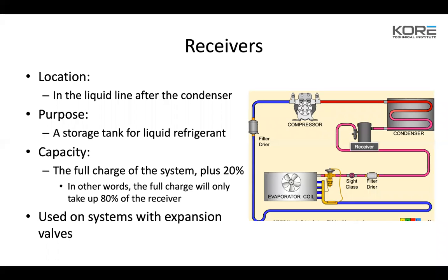So what happens here is those valves hold back refrigerant. If you have a 10-ton condenser, they're going to fill liquid into that condenser halfway through it to turn it into a 5-ton condenser. And that's going to help keep the head pressure up. The reason we want to keep that head pressure up is because we need over a 100-pound pressure drop across the expansion valve to push that refrigerant through it to boil off inside of the evaporator. So that's why we have to maintain that head pressure. The refrigerant is going to want to migrate to the condenser, so you're not going to see it in your receiver. It's going to stay in that condenser because of the valves between the condenser and receiver.